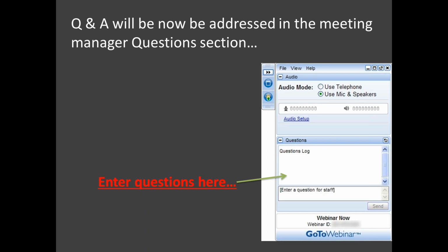Gotcha. So one of the things that goes along with this, at least that I've experienced, is that inside of the parameters dialog box, you can actually steal data and use it for material gains and things like that. There's an example where a customer has a part that's 3/4 inches thick, and it's being machined from an inch stock material. What I've done in the past is create custom parameters and then use the math within that system to define the next upsize, essentially. So like running a floor function.